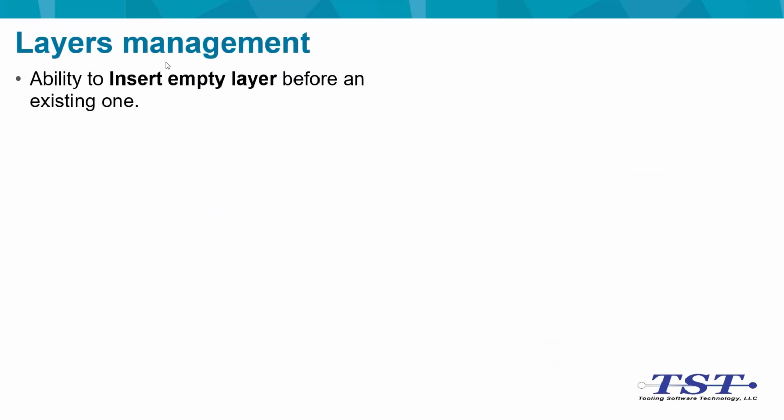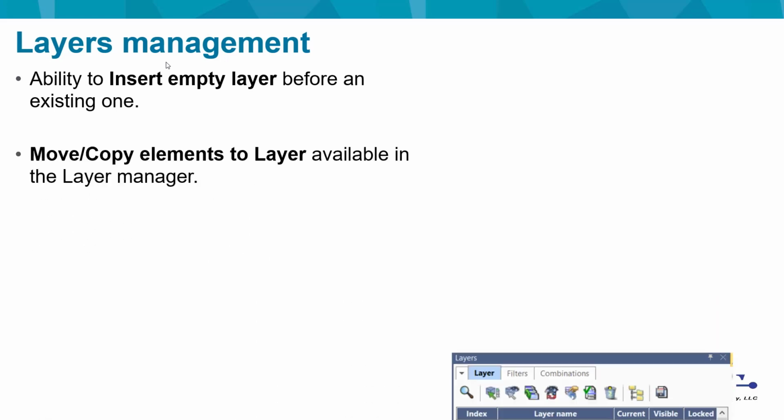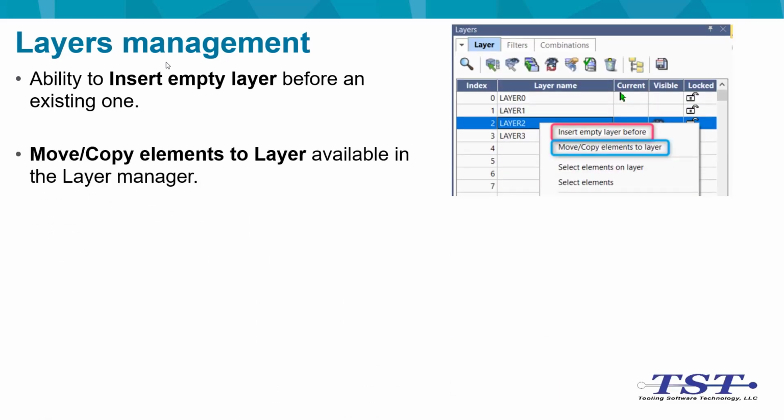Within layer management, additionally to the 2022.0 option, change layer index, there have been some improvements such as insert empty layer before, as well as move copy elements to layer, which is available inside of layer management as well. So here are the new options that you see here.